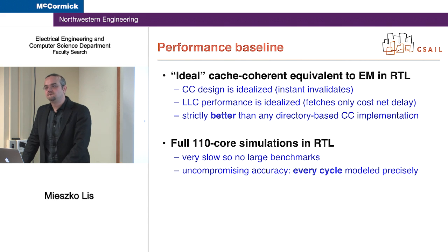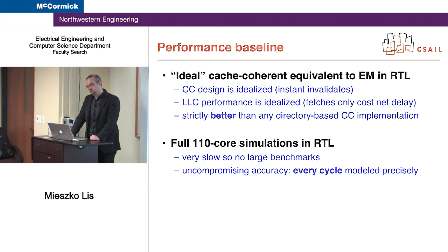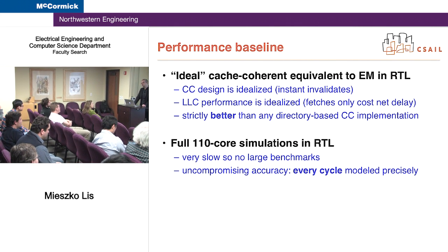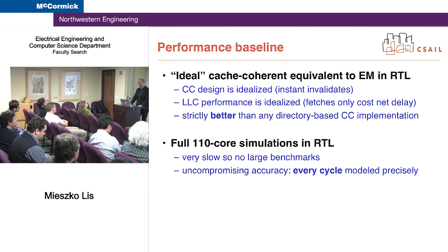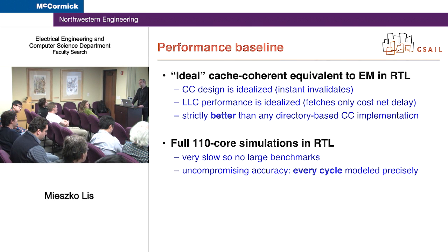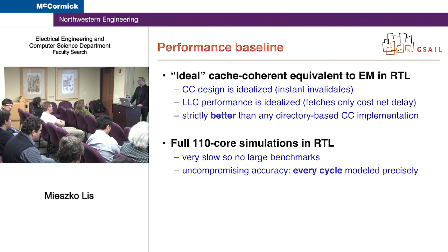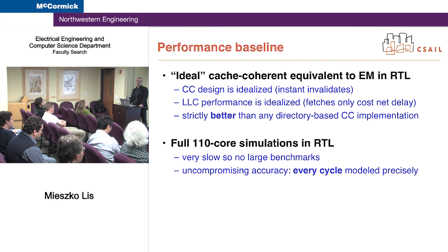So, for example, if you were to have a faster and higher bandwidth interconnect network than the single mesh, would you still implement the migration? The migration would benefit more, right? Because I can afford to do faster migrations with less latency if I have more bandwidth. But it would still be faster to fetch data. Well, it depends. You have to take tens of hops to go around the chip. But if you were to implement it with a butterfly, you can fetch your data in less than 10 cycles. Well, I can implement the same thing using migration.